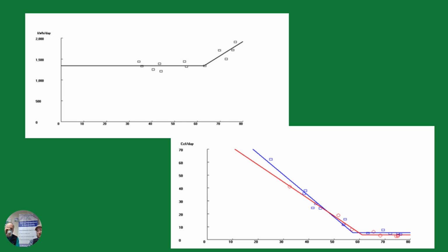In this particular case, we're looking at this same type of weather trend compared to, in this case, it's gas, but we're looking at simply two different time periods, and there's a different inflection point here. That could indicate they made an update to a control system, could indicate they had a failure of a piece of equipment or a degradation of an outside air damper, maybe not getting as much outside air or getting more outside air than before.